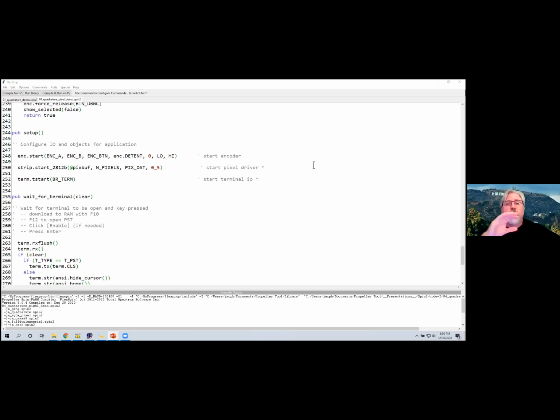Yeah, there's a variety of mechanisms for getting that signal. Again, it's just 2 square waves that are offset by 90 degrees. You see, for example, in the high quality encoders, I'm not sure what's in here. I know it's optical. So it could be a reflective thing. You see that sometimes where you have reflective sensors, or there could be an interrupt sensor as well, where you have a disc with a bunch of vanes in it, and then you have 2 sensors that are offset. And so that creates the thing. And like you said, there are a variety of magnetic sensors that do this kind of output. There's a bunch of it.